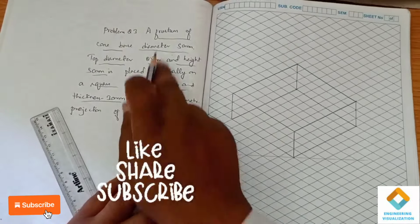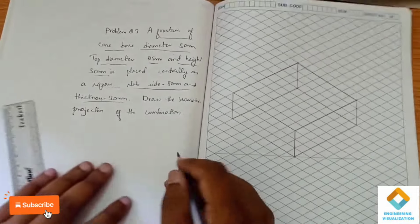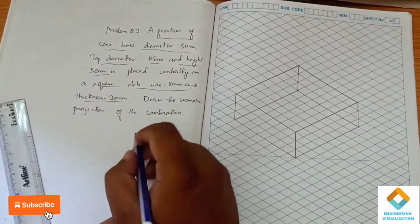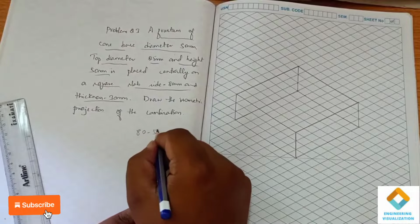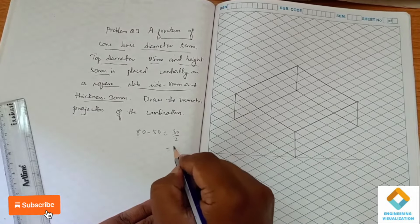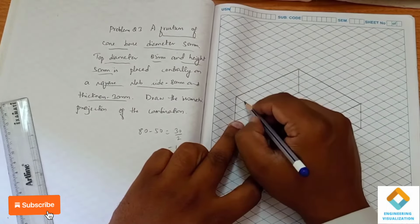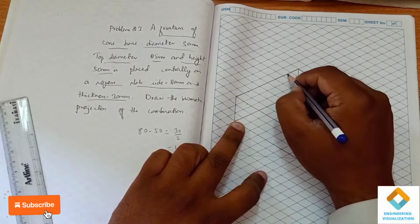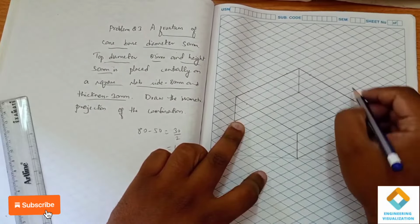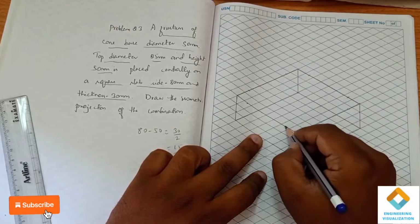Now the frustum of cone, diameter 50. This is 80, so base diameter 50. 80 minus 50 is 30, divided by 2 means it is 15. So 15 on each side.